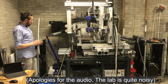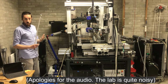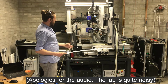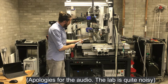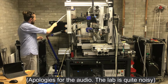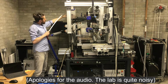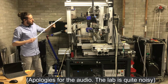And finally, the very last thing to mention is this, which is how seeding particles are introduced into the water. Roughly, what happens is the pump that's sat behind this thing is switched on, and the experiment is up to temperature. You draw some water out from the experiment, draw it into the seeding tank at the top here, and then introduce some seeding powder into here, mix it around, and get it quite concentrated before it can then be reintroduced back into the tank.